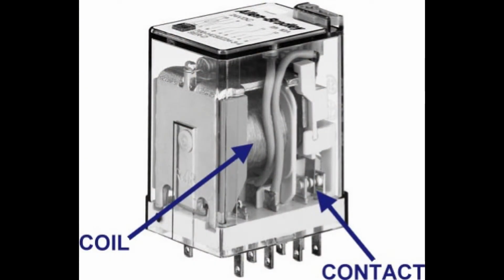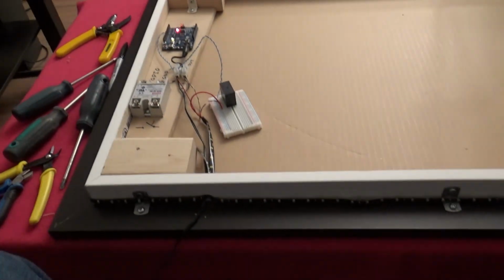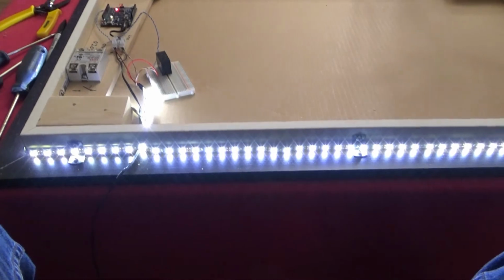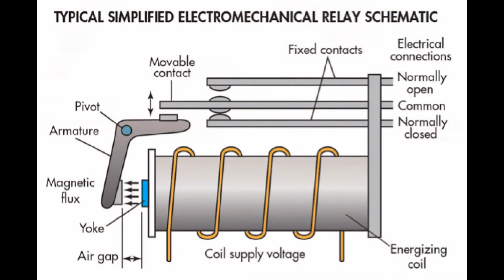Mechanical relays work with alternating or continuous current as an output. However, they are noisy and cannot be switched quickly to decrease the intensity of light because of the response time associated with the mechanical movement. It's a coil which, when letting an input current pass, creates a magnetic field which turns on a switch over the output circuit. The circuit is completely isolated from the input. Normally open relays are found, others are normally closed, and often the two functions are found in the same relay.